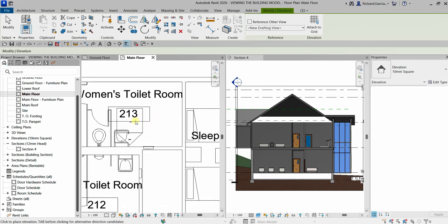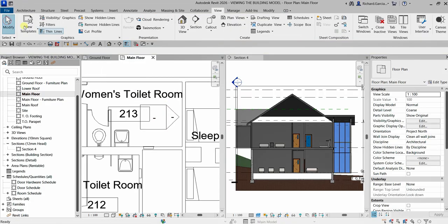Say, automatically as you move your pointer near, our elevation will point to the nearest structural wall. See? Okay, so anyway, I'm just going to place it here. There you go. So there's my elevation, and then I'll select here, modify. If I hover my pointer to that point there, it tells me the name of that elevation, which is 1-1. Views elevation 1-1.